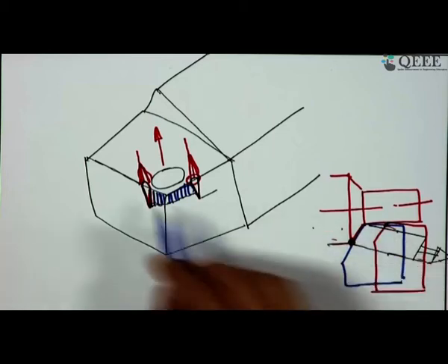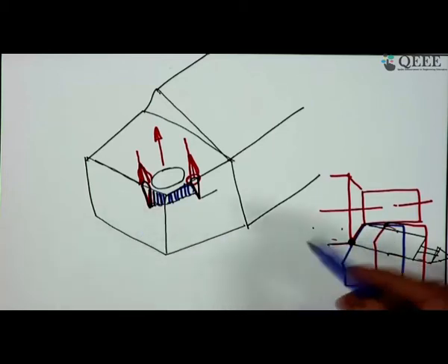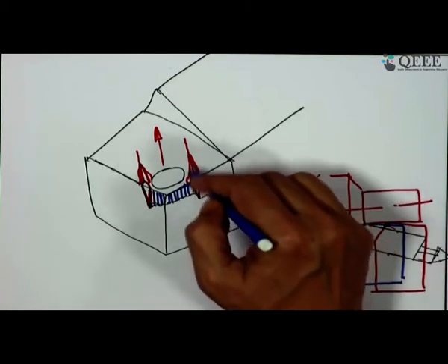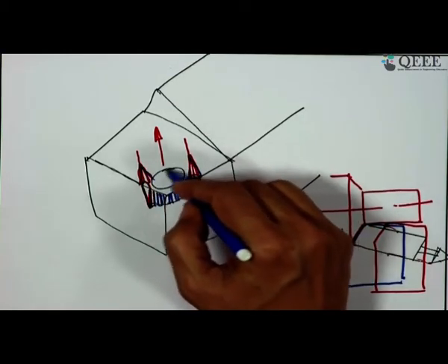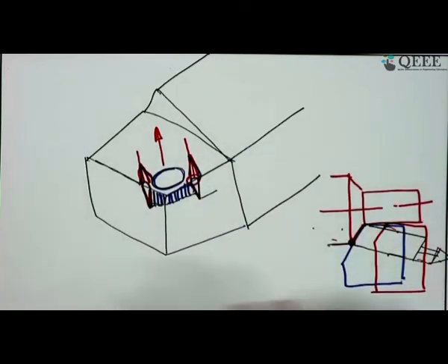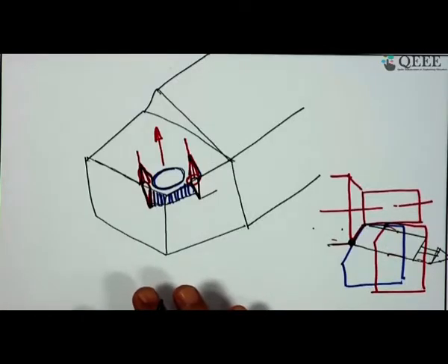Similarly, you have another notch on the border line on the auxiliary side, you have the sliding mark, these are part of the tool wear. Now, this is also sliding wear, these are the two marks, and finally inside you have the crater volume. So, all these features lead to removal of the tool material, and all are very damaging and alarming.